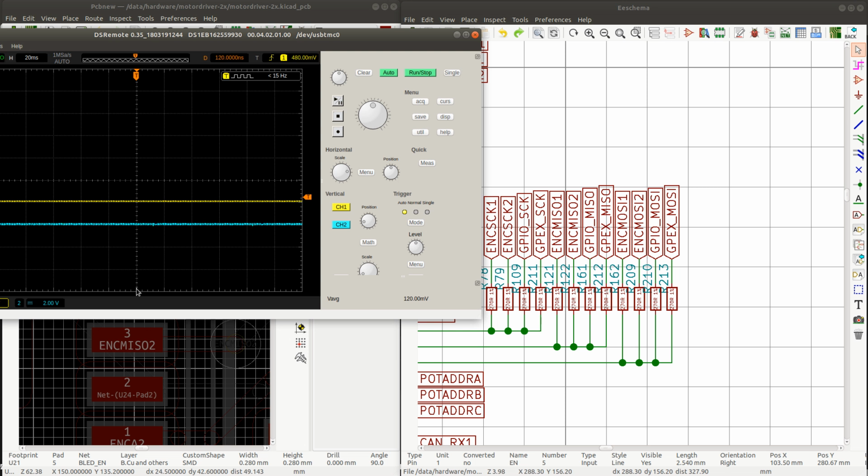Maybe, actually, what's happening is it could be that the chip select is simply not really connected here, and that's why we're not getting anything. The data that is being read is from a different chip, from the GPIO. So this chip select isn't actually toggled, but it still should be high, because if it's not high, then this chip is technically selected, unless I'm just not getting contact with the chip select pin.